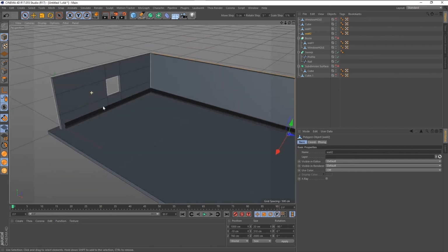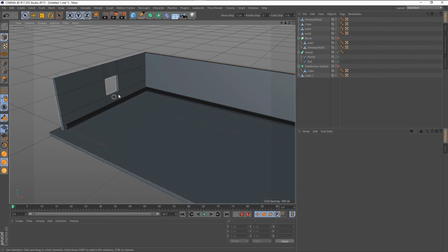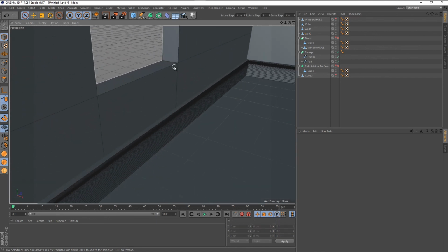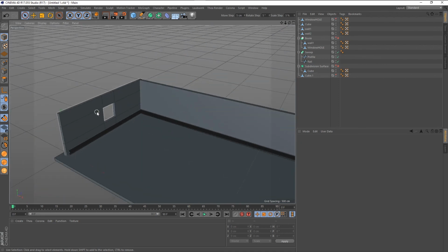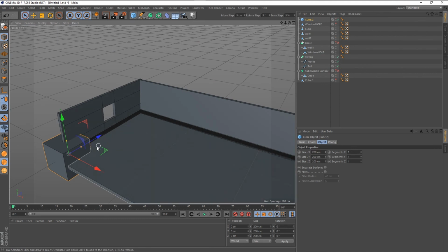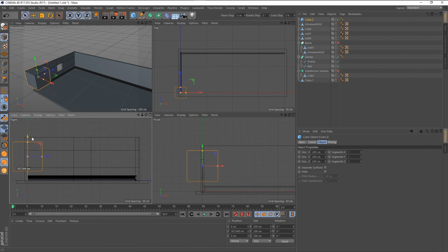Last thing I wanted to cover is bevels. You're going to have to bevel your objects. So let's put a windowsill, for instance, over here. I'm going to put in a windowsill right there. We're just going to put in a cube. We're going to go to front. Well, we can go to right view and go to the wall edge, and I want to get it at the midpoint snap.